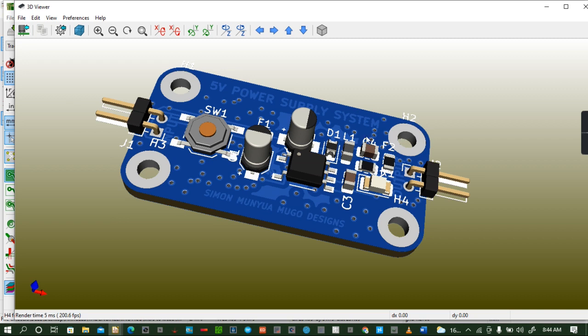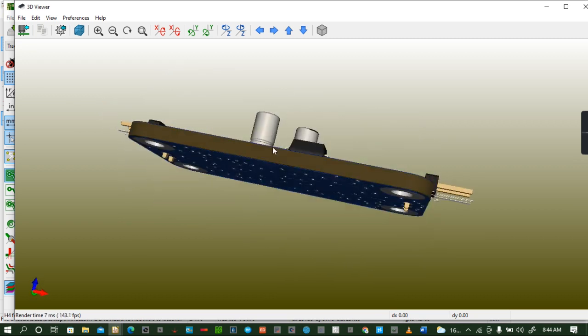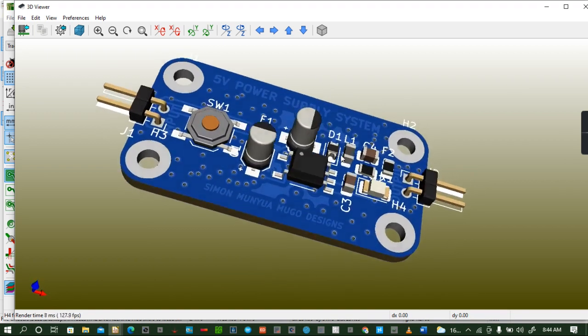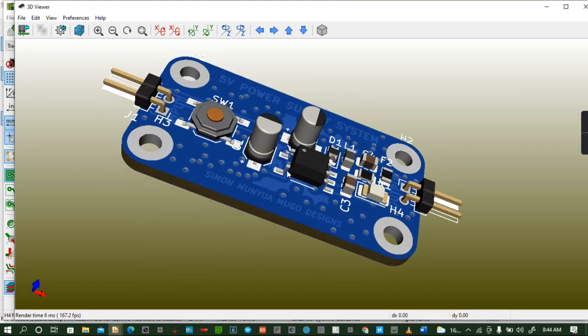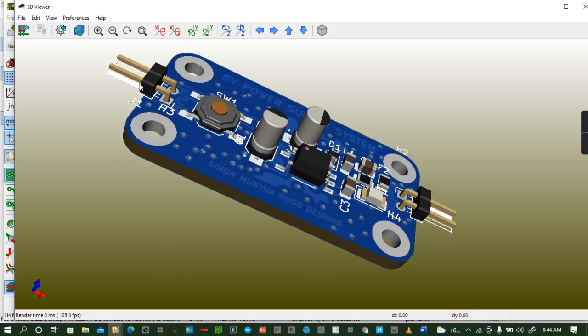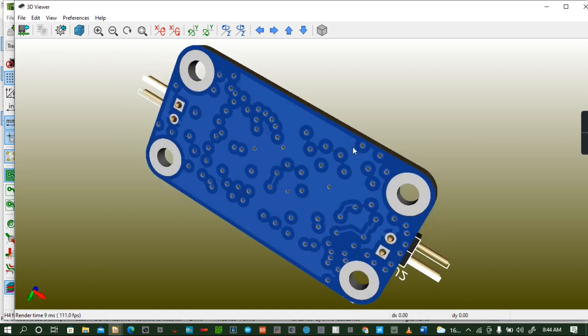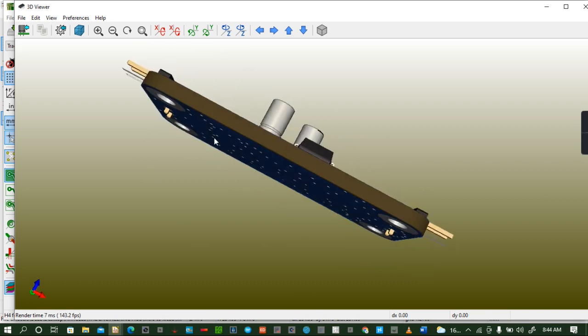And it's up to you to learn how to design them, or how to use them, or how to use your microcontrollers to do your boards, IC integrated circuits. You have to learn how to do the THT PCBs, and how to do the SMT PCBs. For this one, I've done a combination. For example, this connector is a THT, this one is a THT, but all other components are SMT components, surface mount components. You can see they don't have output on the other side, but for the connector there is an output on the other side.